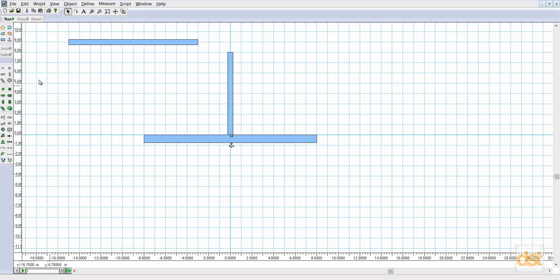If we double click, it'll stay in this mode until we select the arrow tool to exit the mode. So we'll double click the point element, and then click on the bottom center of the beam, and then click on the top center of the post.